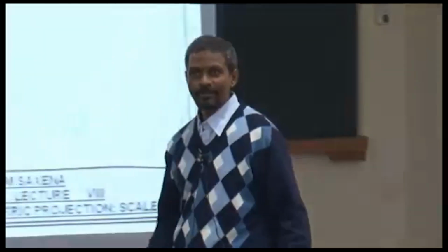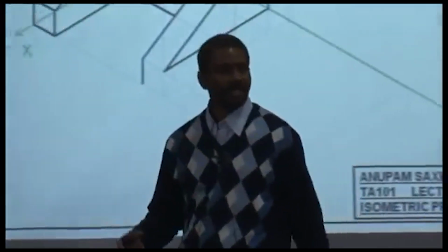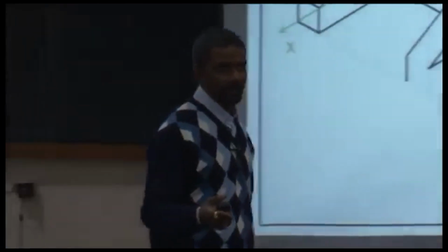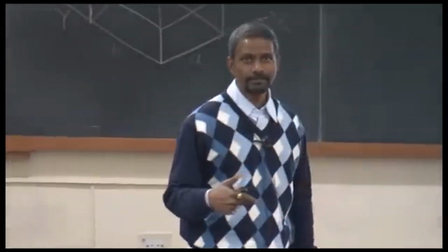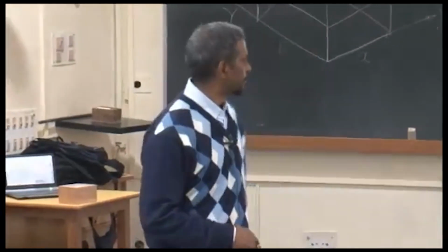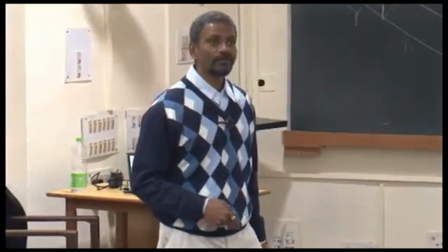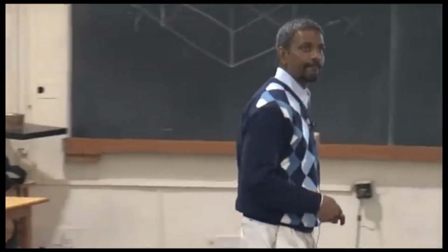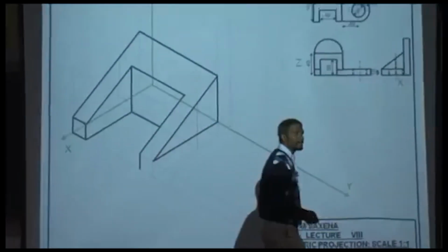Do you remember the 4-center method? You do? Yes? Okay. For that, I need to draw a rhombus that would bound the circle or bound the ellipse. The length of each edge of the rhombus is going to be what? 50.